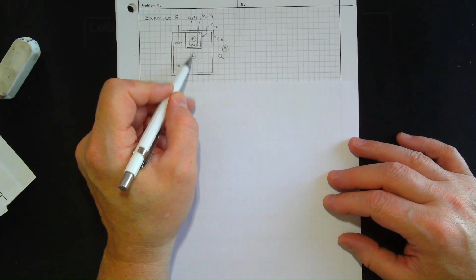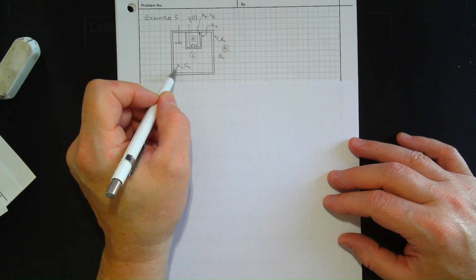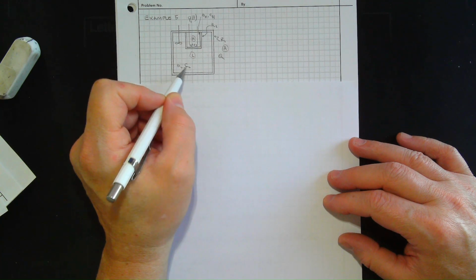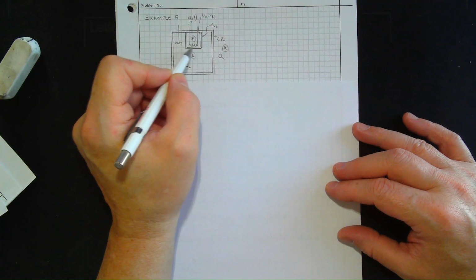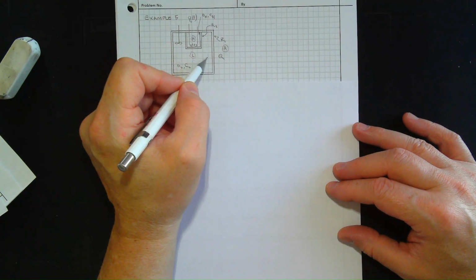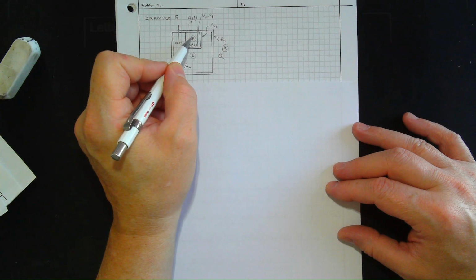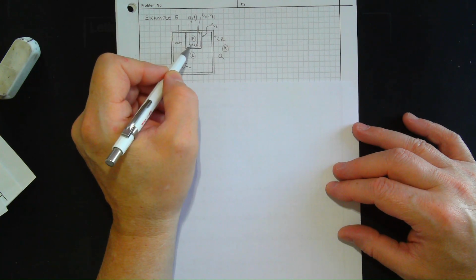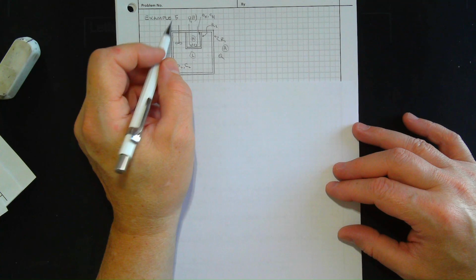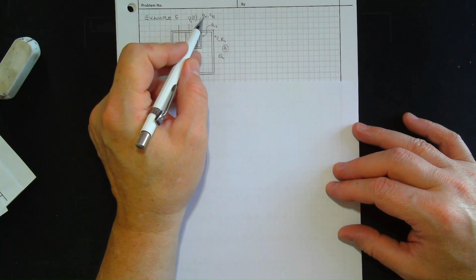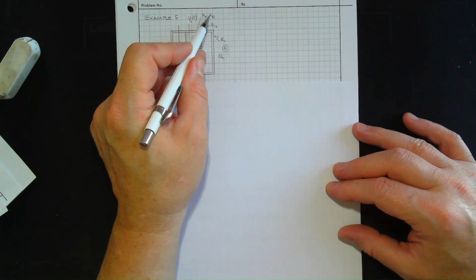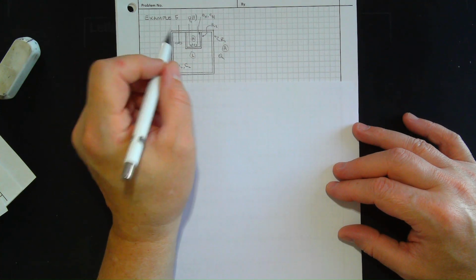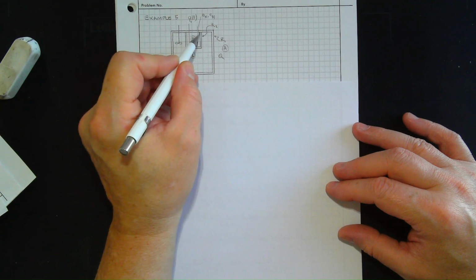This will be the low zone. This will be the hot zone, so theta L and some capacitance CL. And so heat is supplied here, and so heat will be stored here, but the idea is it leaks out into here. So this is the hot zone. So we have heat that we're adding in, but this zone will have a characteristic temperature, and since heat is stored there, we'll look at a capacitance. I'll call that CH.